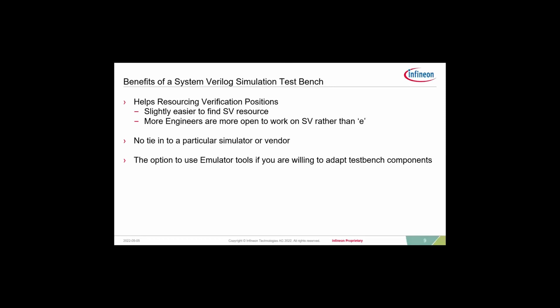Also, there's no tie-in to any particular simulator and vendor when you use SystemVerilog, and we had the option to use some emulation tools. However, that did come with a caveat that we had to adapt some test bench components to be able to support that. But they were the main reasons we changed to SystemVerilog in the simulation test bench.